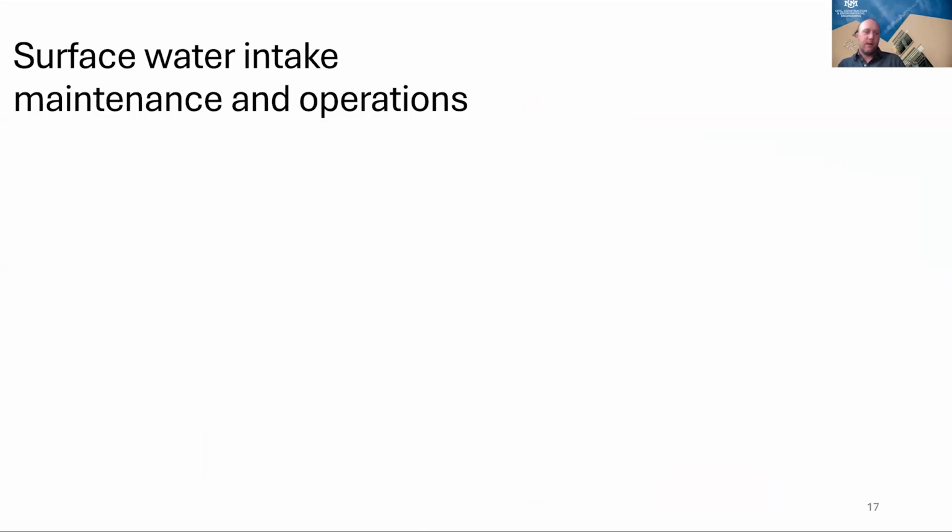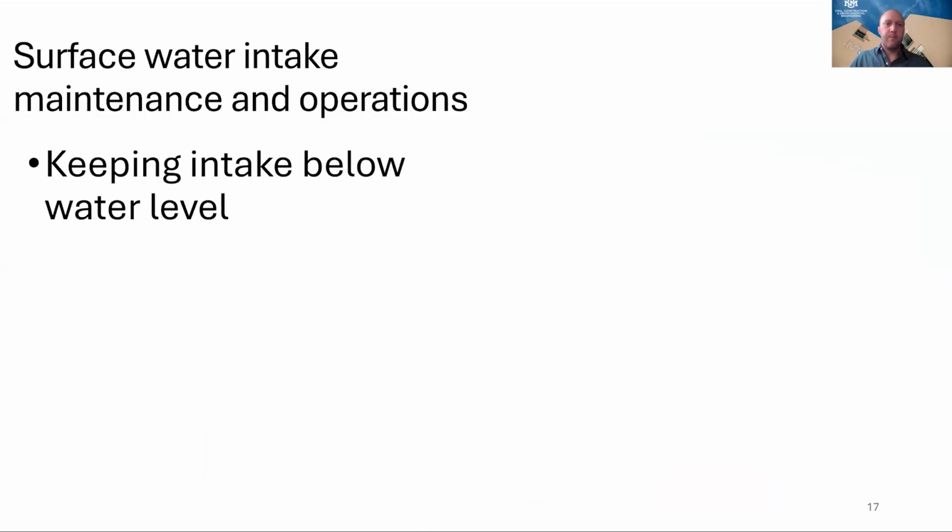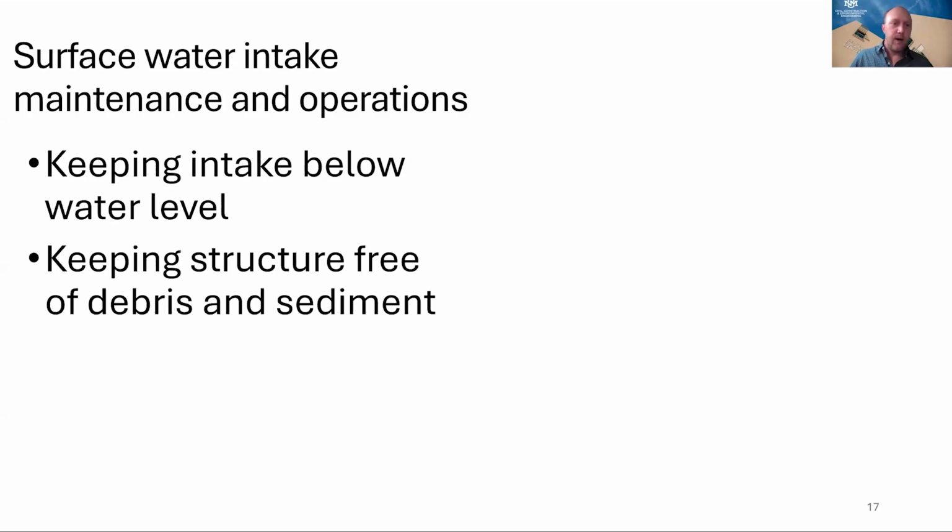Okay, so to talk a little bit about surface water intake maintenance and operations. Of course, we mentioned this before, but keeping that intake below water level is really an issue not just for reservoirs, but also streams. Say that you have a diversion dam that is creating a little reservoir for a stream. There needs to be enough water to keep that full and keep that flowing, and to have that intake sufficiently taking in water. Of course, you have to keep these structures free of debris and sediment.